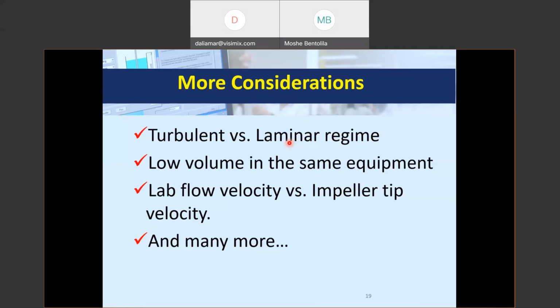And it is very typical, because you want to release more material. You have no volume in the pilot, you need to go from 1 liter, let's say, to 100 or 1,000 liters, and people say, no, use a smaller volume. No, no, no. When you are using a different volume, you need to adjust the RPM again, the feeding time again, the heat transfer again, because it will be different. If you go to a big volume, there is a completely different distribution of energies. Maybe you have another impeller on the same shaft that changes your results. It is a very typical case of success that was maybe not a success: you succeeded in small volume, but when you increase the volume you have a completely different flow, and you thought you were fixed and had finalized your history.